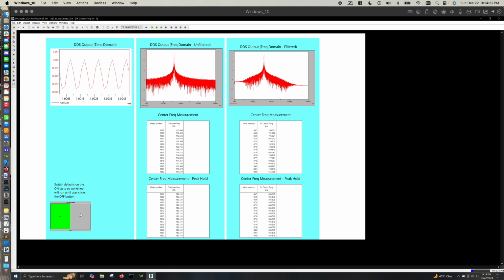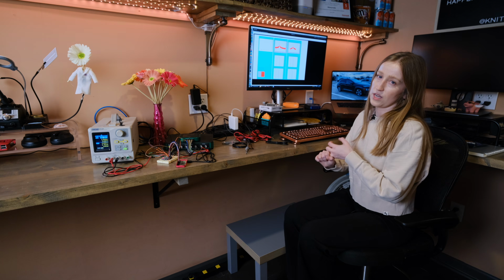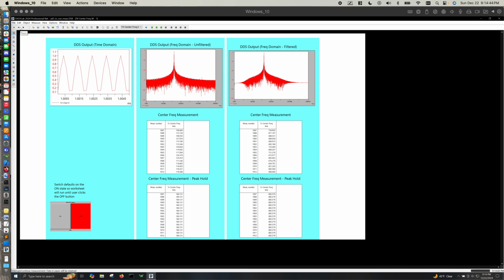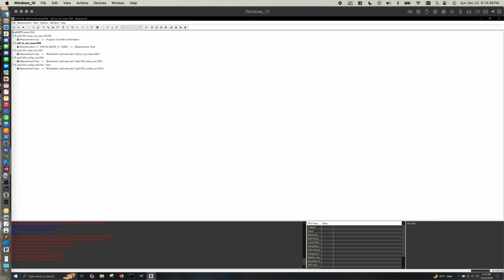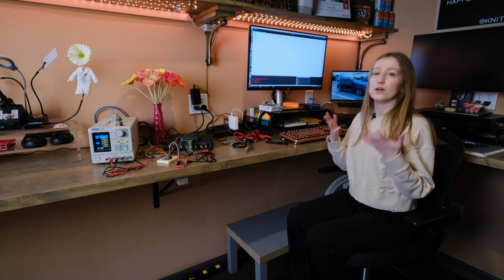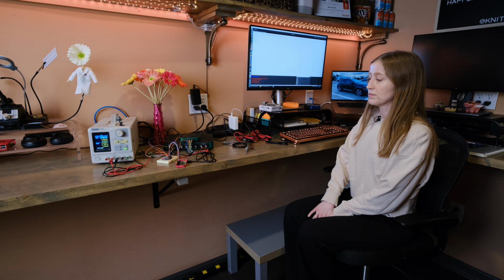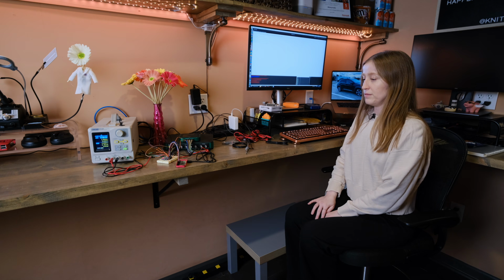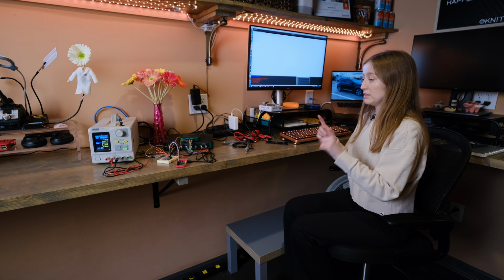So if I hit off, that will stop this particular worksheet, and it will stop the overall sequence. You can see, again, the stop button and the pause button are now grayed out, the play button's green again, and if I go back to sequencer, same thing, and it's ready to run again when we're ready. Although, because I do have the Raspberry Pi script separately, I do need to shut my Raspberry Pi off and reboot it. Anyway, that is a crash course getting started with DASYLab 2024.